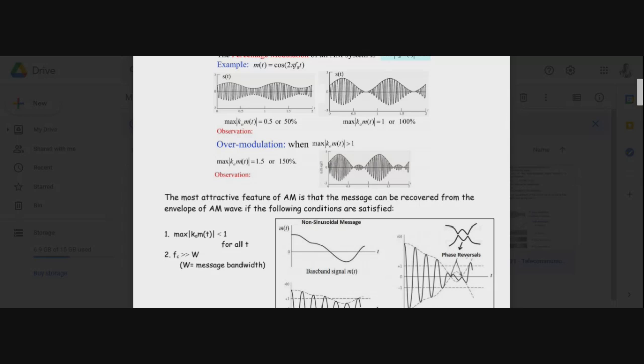So it will go up as the envelope is going up. Then when it hits zero, it starts going up again, but this time it will go up slightly, then back to zero, and then up. So the envelope will not be what you want, because what we want is that the signal would have gone down, crossed zero, and then gone up. But the envelope detector doesn't do it. That happens when you have too much modulation.